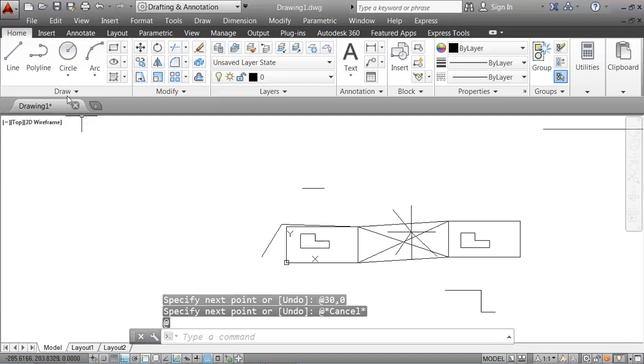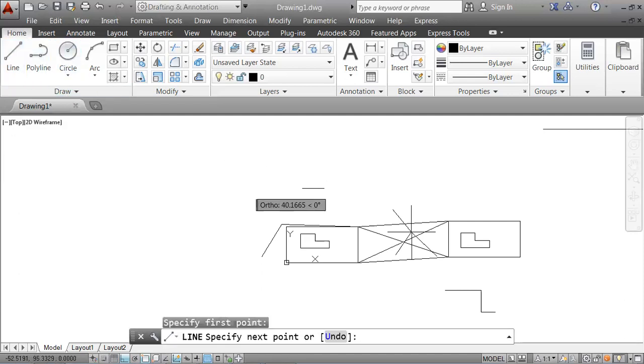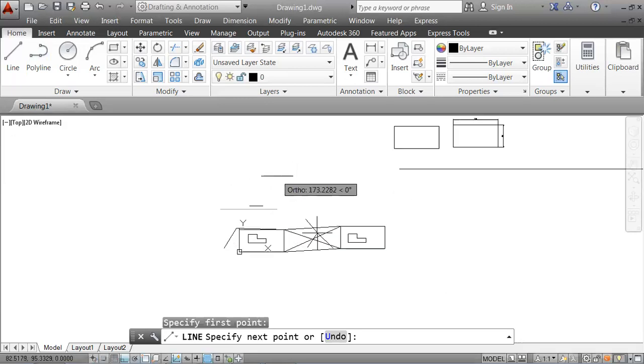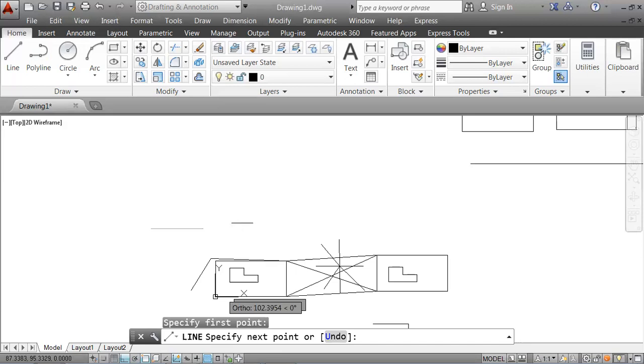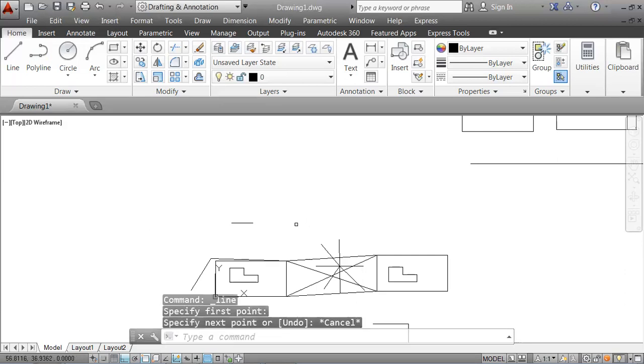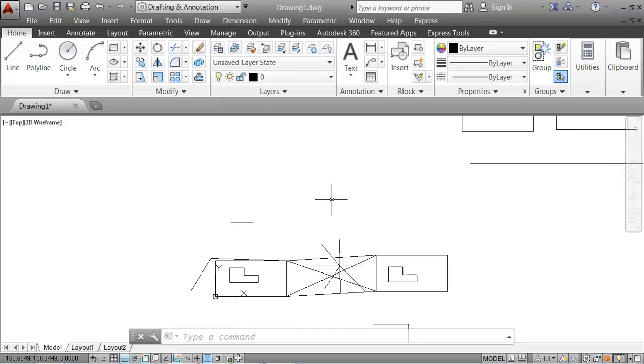The last one was the absolute, clicking in the line. You need to know the coordinating point. For absolute, you have to start on 0. You need to remember 0, 0 in order to know the coordinating point. Always you need to know what is the coordinating point that you're going to start the line. When you know the coordinating point, add the recommended value you wanted for this. All right. All these are the 5 main methods that we recommended to use for AutoCAD.